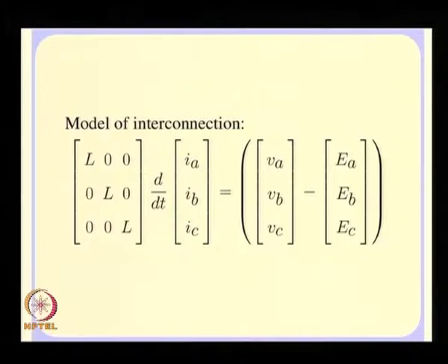Now, coming to the system we are going to study. In the last simulation which I had shown you, I had a synchronous machine which is synchronized directly to a voltage source, okay, and that was the simplest system I could have shown you for this synchronization. In order to show AVR action, of course, it does not make sense to synchronize a generator to a voltage source, because if you have connected a generator to a stiff or constant voltage source, there is no question of voltage regulation, because the voltage is maintained by the voltage source itself. Okay. So, voltage regulation makes no sense